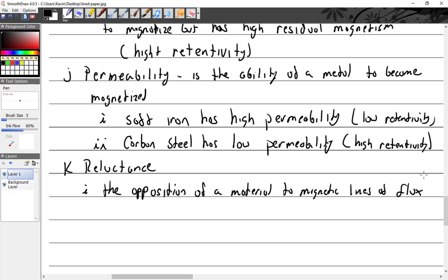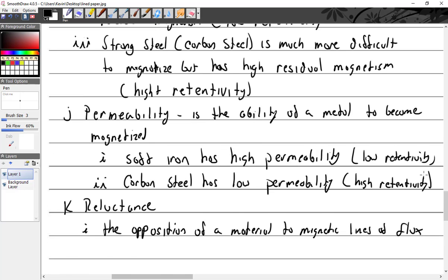But as far as the magnetism goes, we're going to circle back around. We're going to talk about ignition now. But when we come back around to it, we're going to talk about why it's made the way it is. So at its core, it's got a magnet. Do I want that magnet to be soft steel or hard steel? Hard steel, so it retains its magnetism.